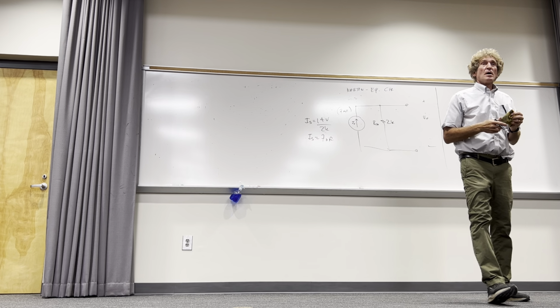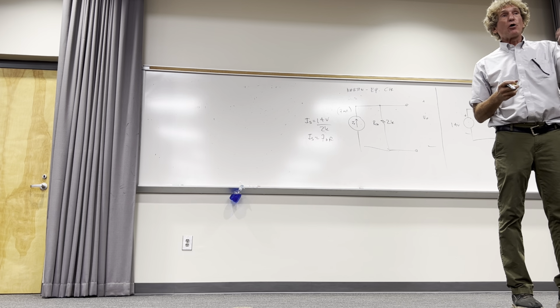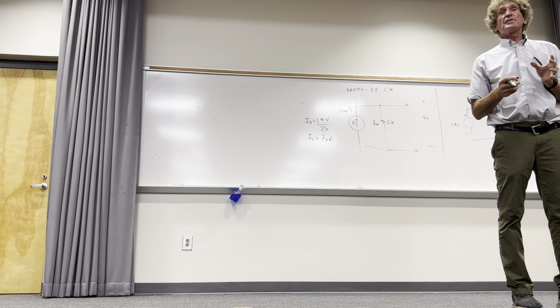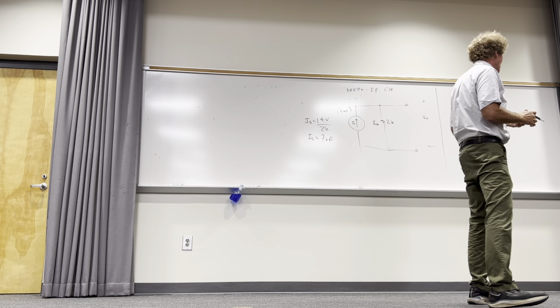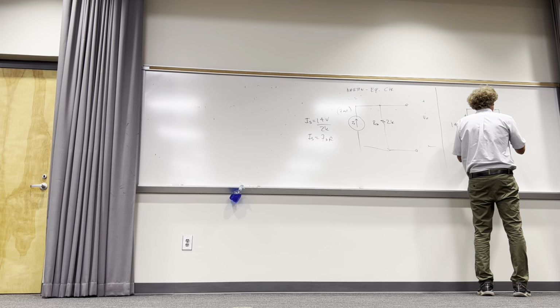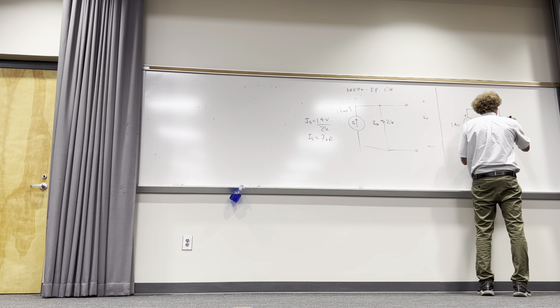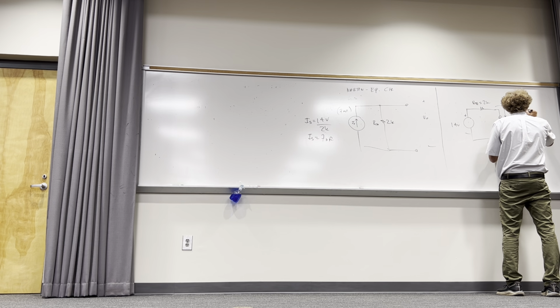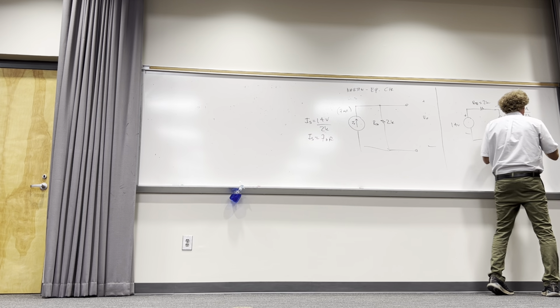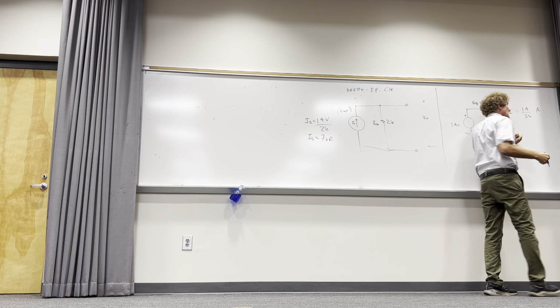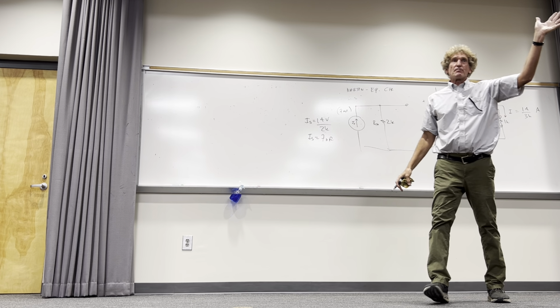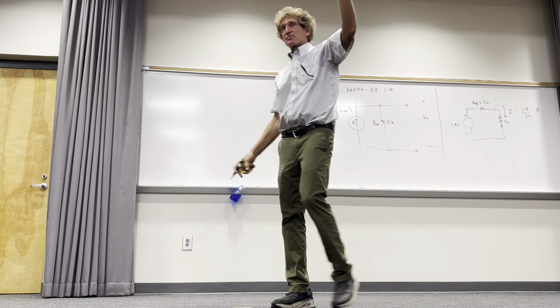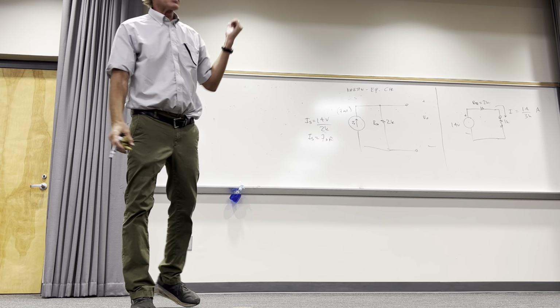And now I'm going to attach the same load as before. You all follow me? I'm going to prove you get the same answers with both of them. So more to this, but I want you to see this part. So now when I put in 1K here, I knew that this current would be simply 14 over 3K amps, or really 14 thirds milliamp. How many see that, first of all? Make sure you see that, what I'm talking about. That's from last time.